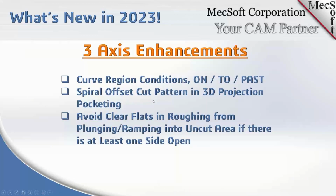Now, what are we doing in 3-axis enhancements? This is a really cool option. If you were familiar previously, you could do end conditions when you're selecting surfaces to machine, and it would calculate an end condition based on the perimeter of the surface. So now you can actually use those end conditions on a curve region as well. So there's no need to select the surface, or if the surface is not great to select where you want to machine, just draw a closed curve, and then you can add your on, to, and past conditions to the curve.